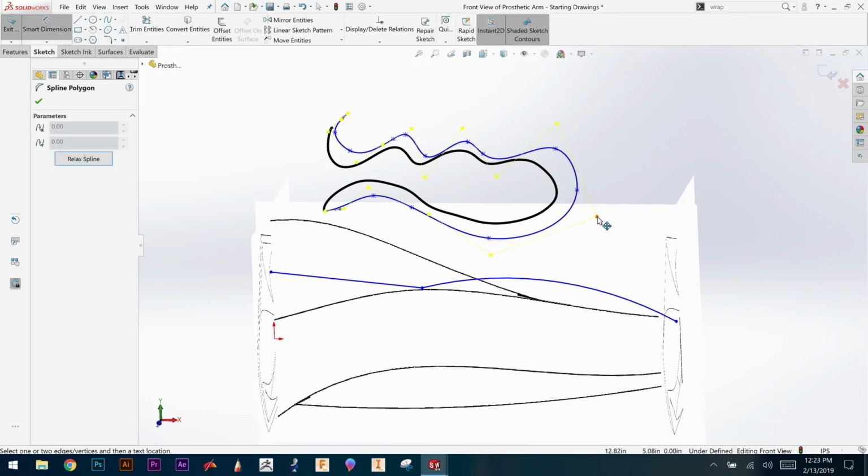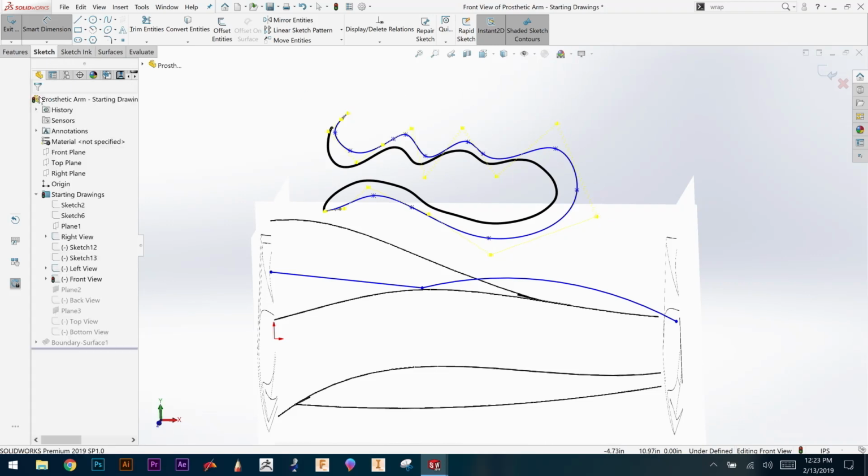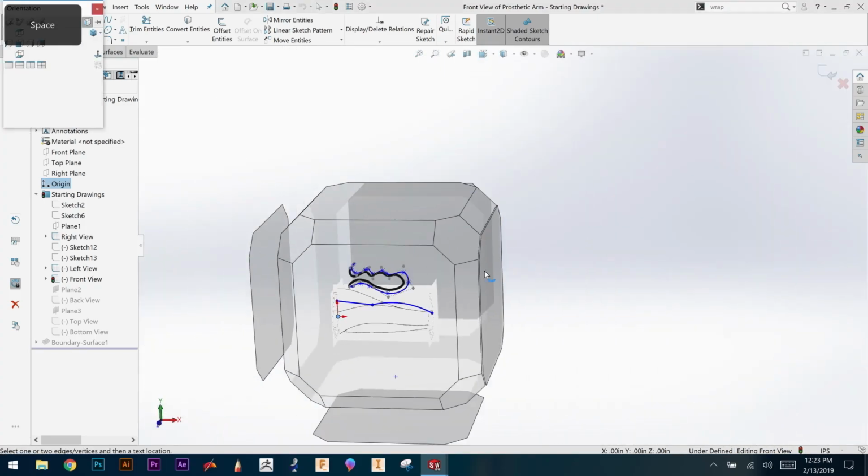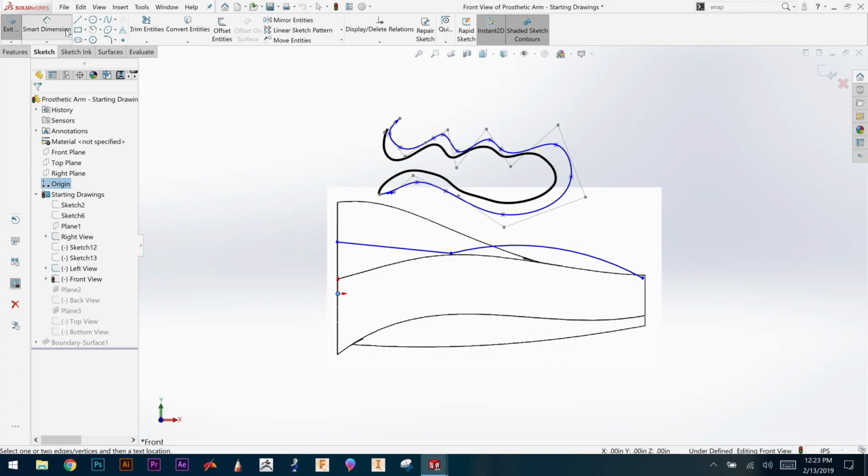Let's just try it real quick. Doesn't seem to want to. Or try from the origin, to a specific point. Well, I am in 3D right now. Maybe that's part of my problem. That's a good question, though. I actually haven't done that myself. I'm not sure it likes that at the moment, but I think you can do that for style splines, not standard splines. The style splines have construction geometry. So I guess the answer would be to convert it to a style spline if you can, and then use your dimension tools.